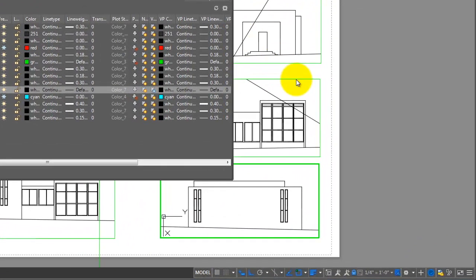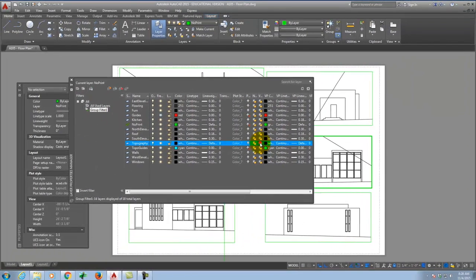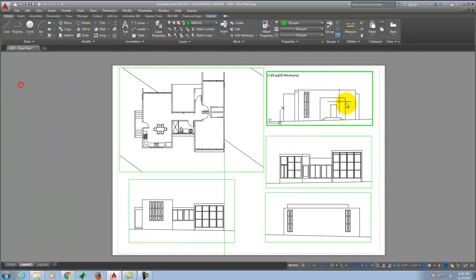So if, for example, I had a 2-story building, I would draw both stories one on top of each other. And then in the viewport, I'd turn off the first floor and leave the second floor on, and then vice versa in each of the views. Right? So you're doing that control at the viewport level, which is a lot easier. So let me go ahead and once again, we'll turn off there, and we'll turn off there, so that those topo lines aren't showing through.